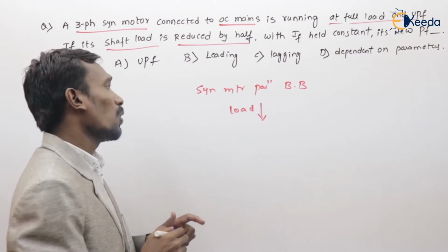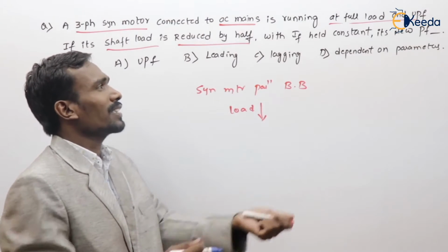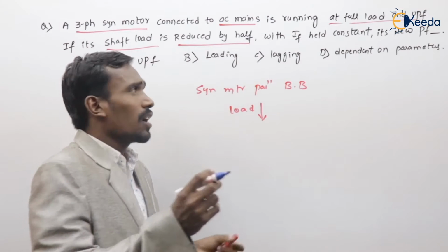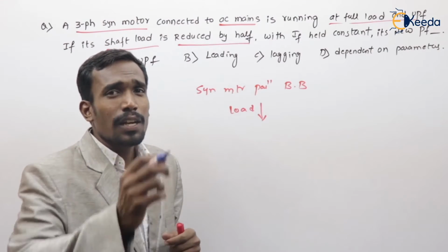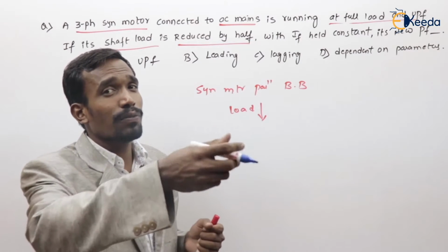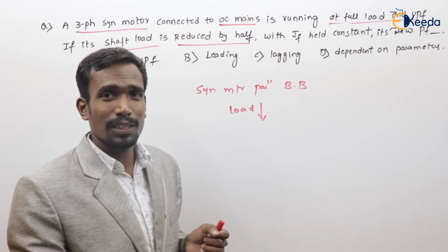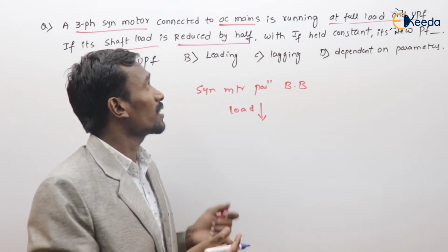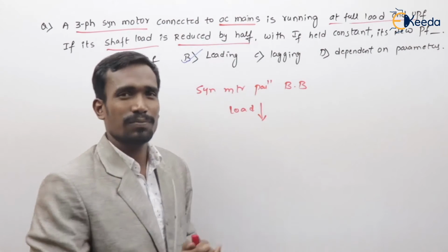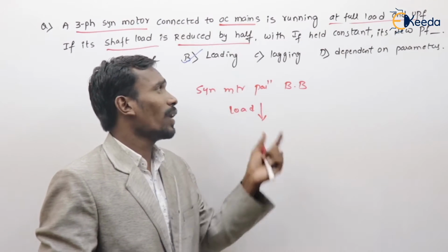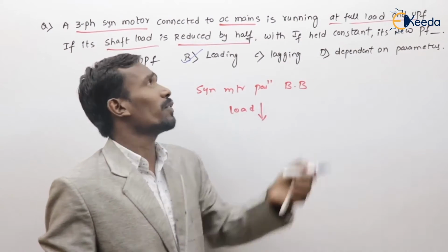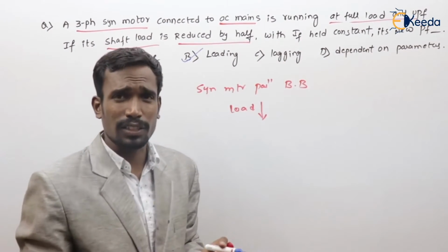reduces, then what happens to the new power factor? In a synchronous motor under unity power factor, if load reduces, then power factor reduces, but is it lagging or leading? It is leading. When the load reduces, the machine operates at a new power factor that is leading.